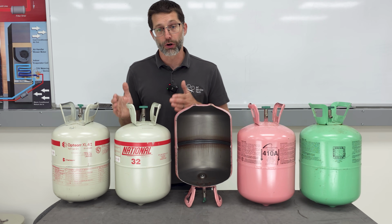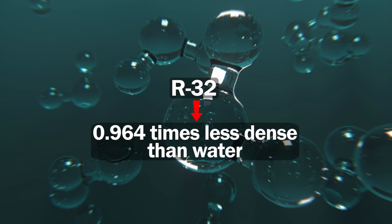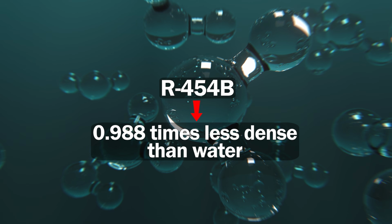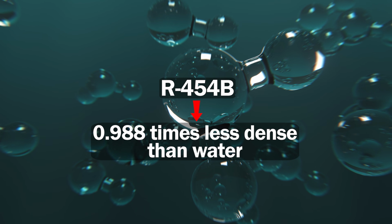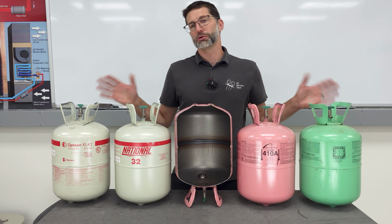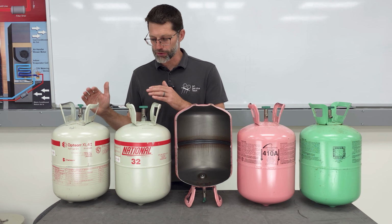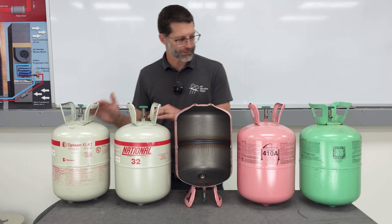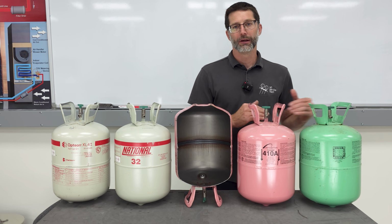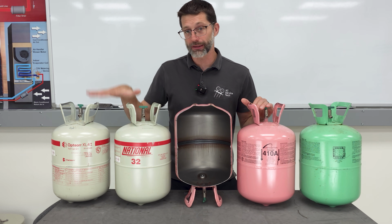So for R-32, it's 0.964 times as dense as water. And for R-454B, it's 0.988 times as dense as water. So anyway, the long and short of it is that the same volume of liquid refrigerant over here weighs less than with these older refrigerants. And so you just want to be aware of that for when you're buying these new refrigerants.